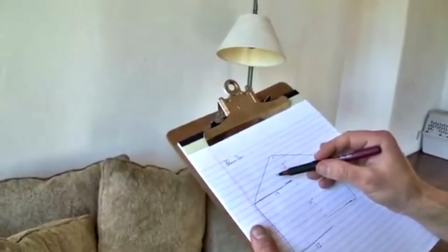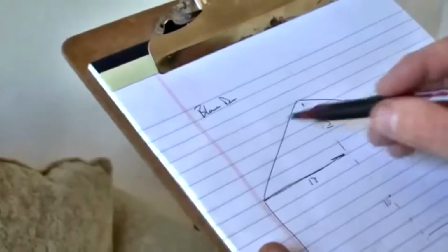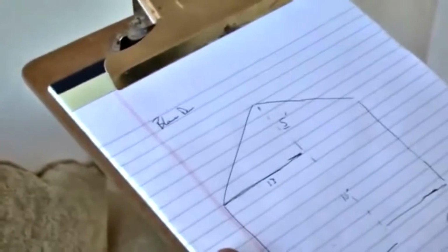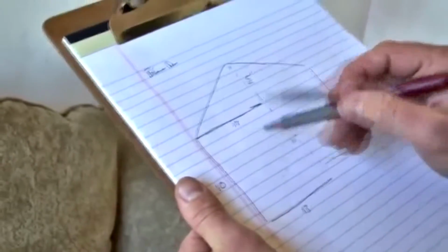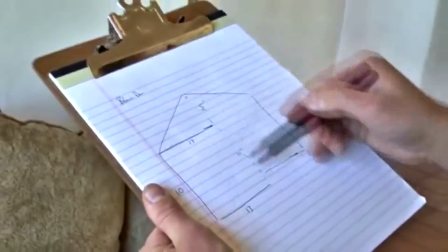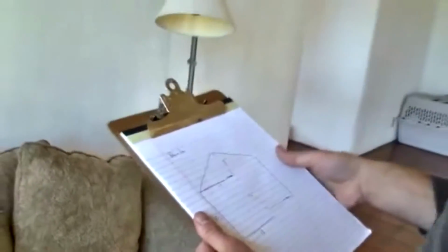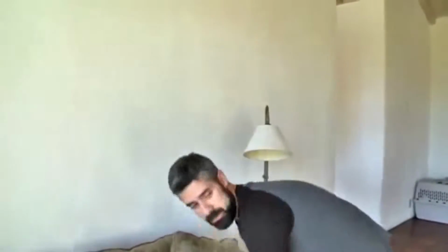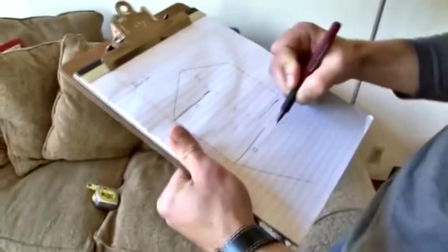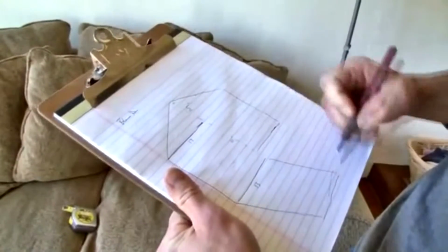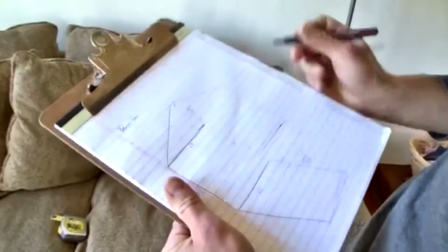Now when you're calculating the square footage of a triangle, it's 1/2 base times height. So in this case, it would be 6.5 times 5 to get the square footage of that area. And this, of course, is 10 times 13 to get the square footage of that area. You add those two together, and you have the square footage of that entire section of wall, which we can multiply by the length of this. Let's see what we're at here. And so then I'll draw a line here representing my length at 232 inches.